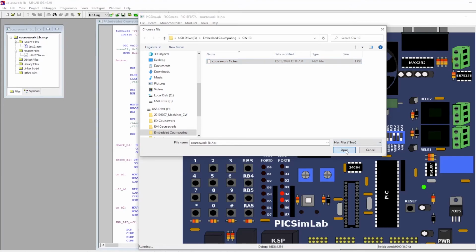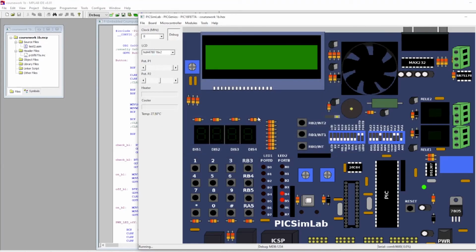Okay, so before that, first we need to turn on the ports: RA0 is for the potentiometer, and then RC2 for the fan, and then RA5 for the display 4, we need to display the state, and then port B for LED. Okay, then RB4 and RB5 light up because we set them as an input. Okay, so now I will press RB4 to enter the first state. Here it shows 1, indicating it entered the first state.